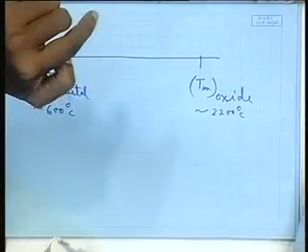So, what happens is, if you try to cut, immediately, as you know, aluminum's exposed surface is nothing but oxide, alumina, Al2O3. That Al2O3 gives it corrosion resistance and protects it from further corrosion, because Al2O3 is quite inert in nature. So, if you want to cut it by gas, what will happen? That layer will only thicken, further Al2O3 will form, and as you can see, before we could reach 2200 degrees centigrade, much of the plate will attain more than 600 degrees centigrade. So, we will have molten metal inside, the outside will be a solid, thick crust of alumina, and inside the metal will be in a molten state. Or in other words, what will happen to the plate? The plate will just crumble.